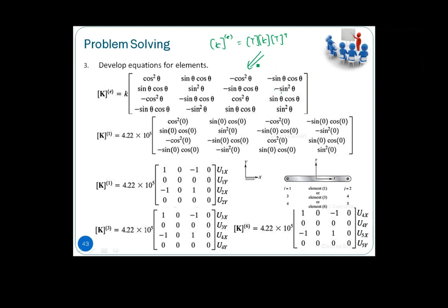Okay, here we are looking into 4 groups, right? Element 1, element 3, and element 6 have theta equal to 0, horizontal. If you substitute theta equal to 0, then we have the so-called stiffness matrix. It's basically similar to what you have seen in axially loaded members. U1x, U2x is 1, negative 1, negative 1, 1. Y has no displacement. So that basically gives us the first element.